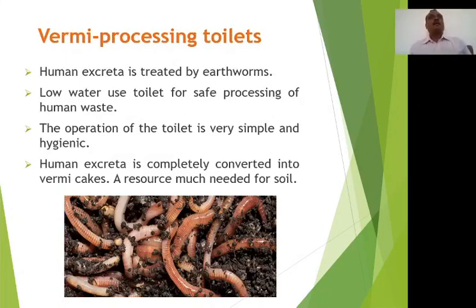Vermi processing toilet. It is a design of toilet in which human excreta is treated by earthworms. It has been tested in India. Operation of such a toilet is very simple and hygienic. It is a low water use toilet, and the human excreta is completely converted to vermicast, which is a resource much needed for the soil.